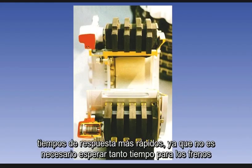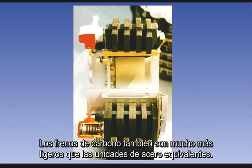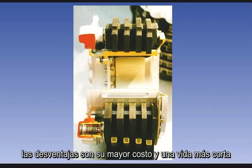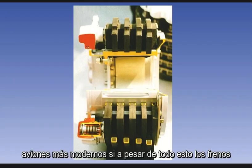It also allows for quicker turnarounds, as it is not necessary to wait so long for the brakes to cool before taking off again. Carbon brakes are also much lighter than equivalent steel units. The disadvantages are their increased cost and shorter life. However, the advantages outweigh the disadvantages, and they are now found on most modern aircraft.